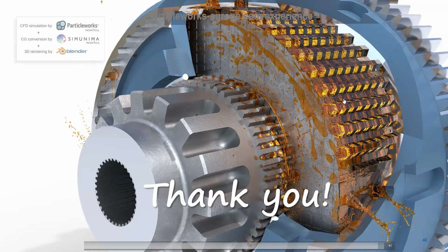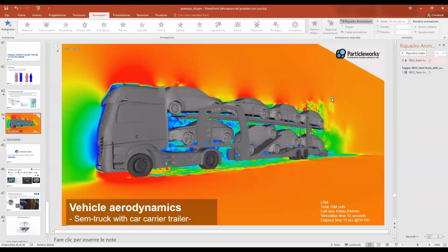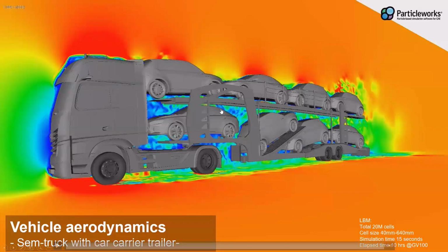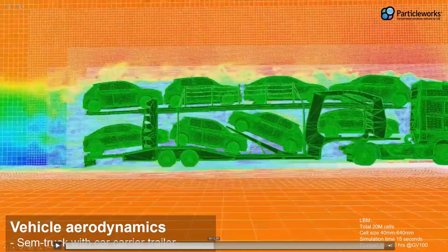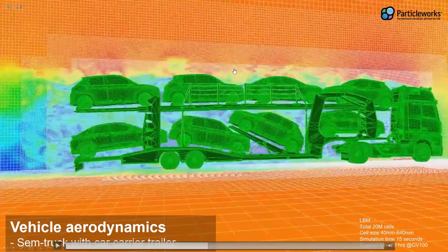And the other question is about the finite volume method. So how can FVM be meshless when coupled with Particleworks? It's meshless, basically meaning that we don't have to think about the mesh generation, because as you can see here, at the beginning of the simulation, there is a Cartesian grid automatically computed and handled by the software. So it's meshless in that regard, okay?